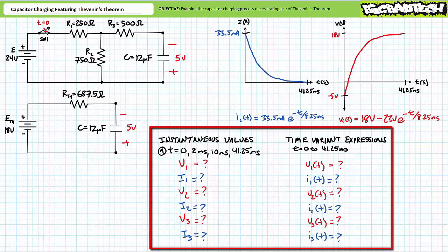If you recall, this is an occasion in which we know the instantaneous voltage across the capacitor to be approximately 11.2 volts, and instantaneous current through the capacitor to be approximately 10 milliamperes. Finally, solve for the instantaneous values for all these properties when voltage across the capacitor happens to be exactly 0 volts at t equals roughly 2.022 milliseconds. This is an occasion in which we know instantaneous voltage across the capacitor to be exactly 0 volts and instantaneous current through the capacitor to be approximately 26.2 milliamperes.